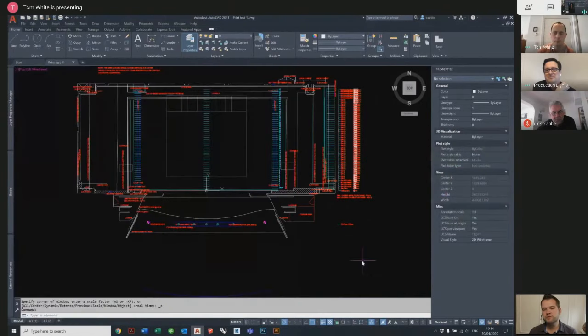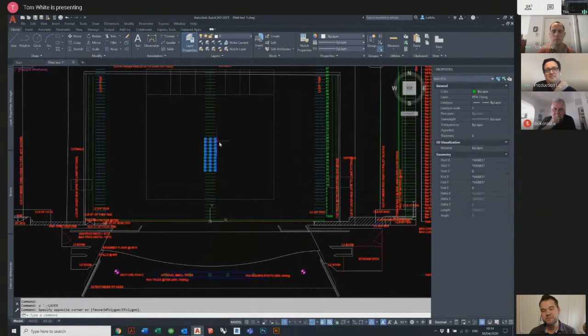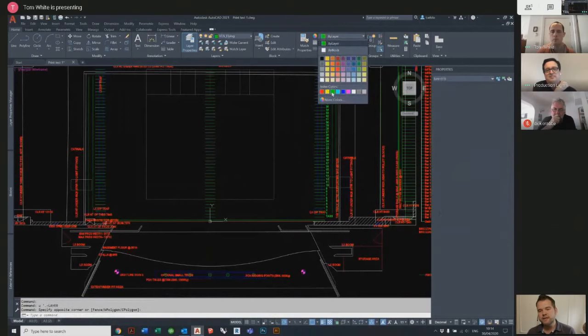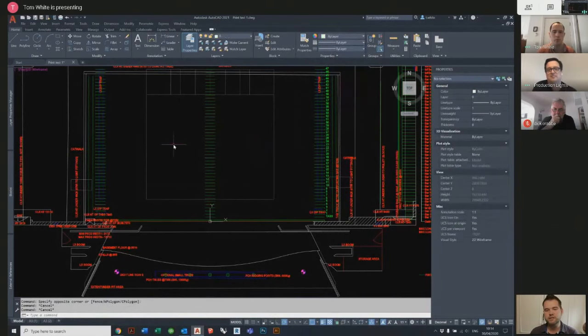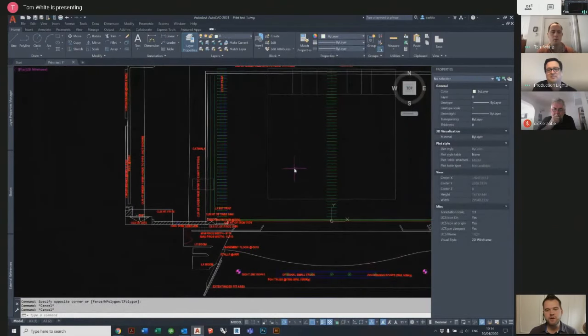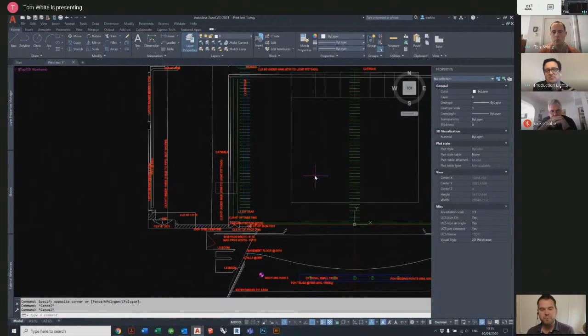And again, that's where, if you've organized your drawing properly using the layers, and if you created things using the blocks properly as well, then all of that will just change right over your drawing. Whereas if someone says, oh, could you just print this out for me, please? Because they know that you do CAD, but someone else has actually produced the drawing. If they haven't done it properly, then that, oh, could you just print this, suddenly becomes a 5-hour job while you try and tidy up the drawing first to get it into a place that it can be printed in a useful way.